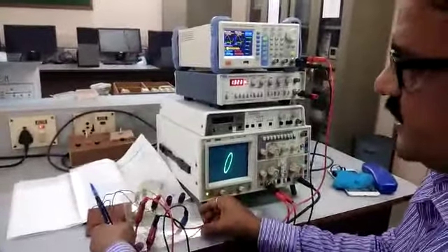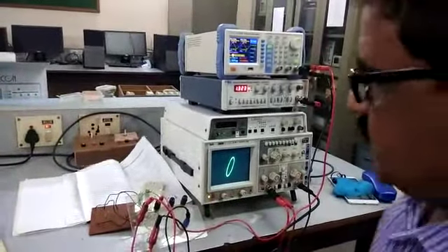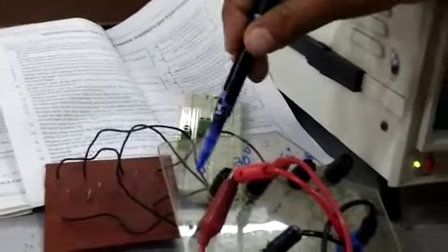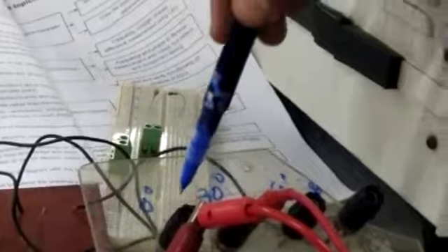This is my RC phase shift network. Why do we require this RC phase shift network? Because here we know the phase at 0, this is 30 degree, 60 degree and this is 90 degree. Means there is one RC network, and each RC network generates a phase shift of 30 degree. The second is in series with this, then 30 plus 30 is 60, then 60 plus 30 is 90. In this way you can select the phase from this RC network.